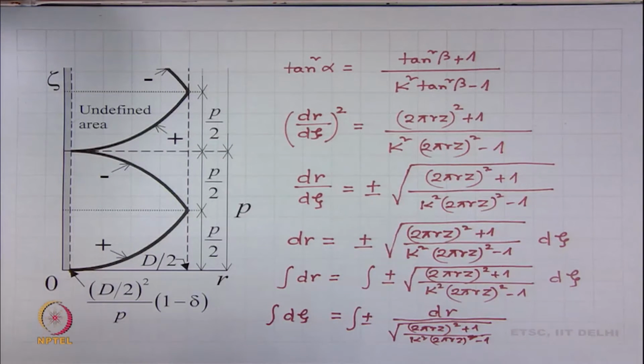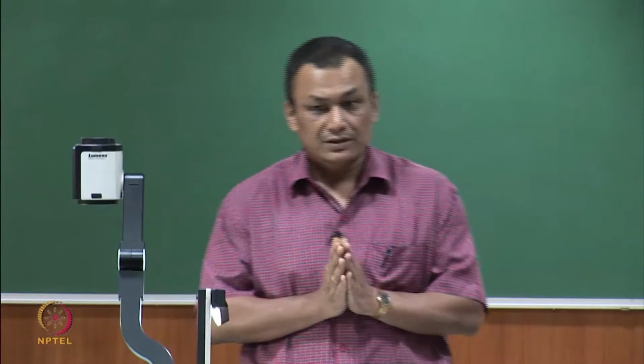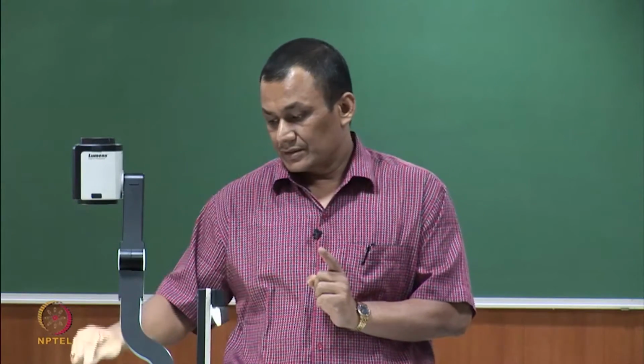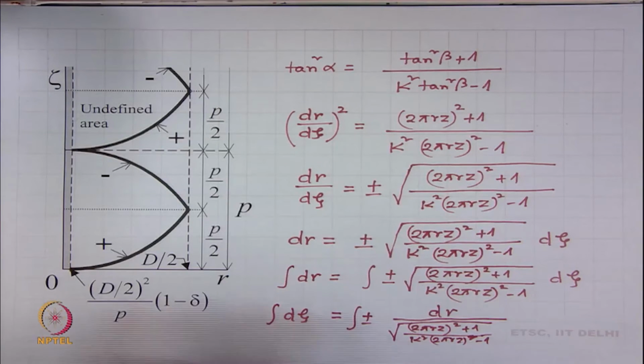So, the fundamental expression of radial fiber migration as per Taylor's model has two problems. One, it is not possible to obtain the fiber path of a migrating fiber analytically. Second, fiber path is also not defined at a too small radius.